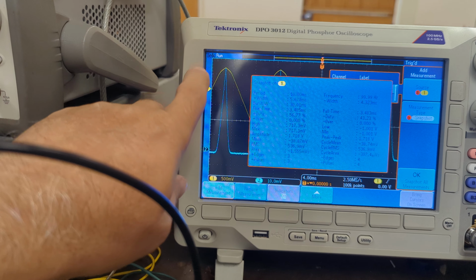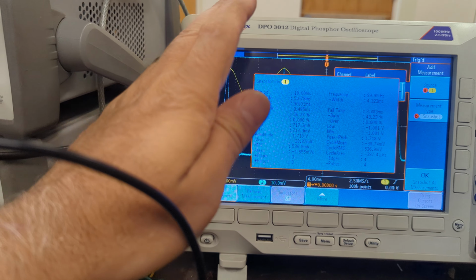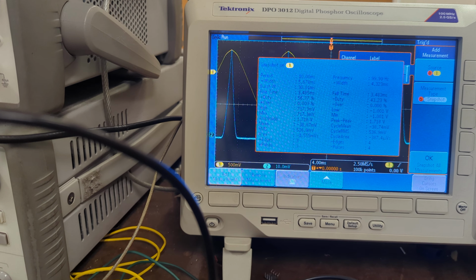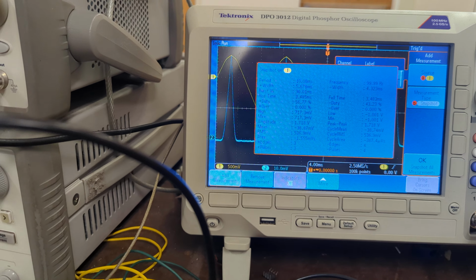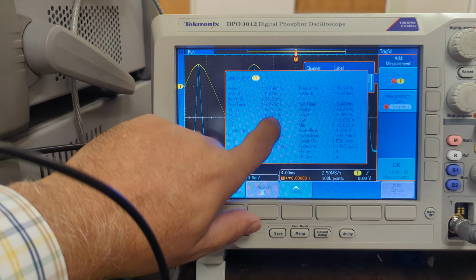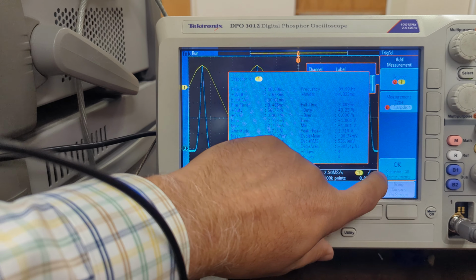So this voltage is representing current, and notice it's getting sharper, and so the whole device is getting a resistance that's getting smaller with voltage, and the function generator just can't keep up. So really about 700 millivolts is all we can get.